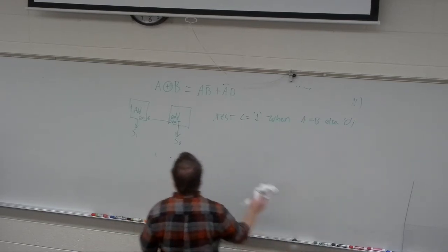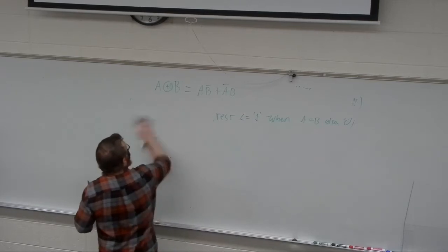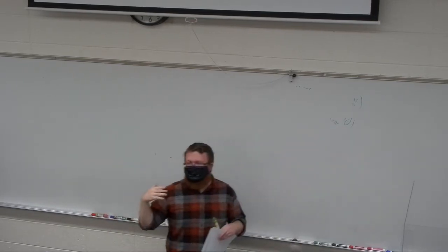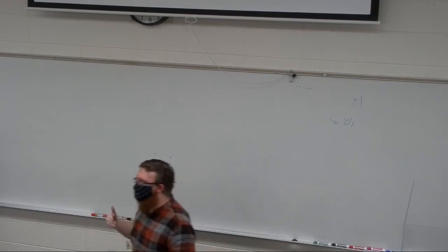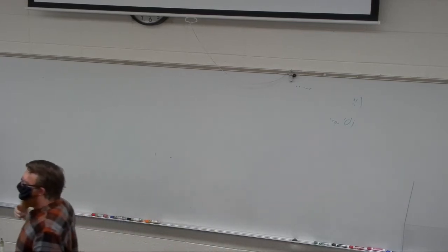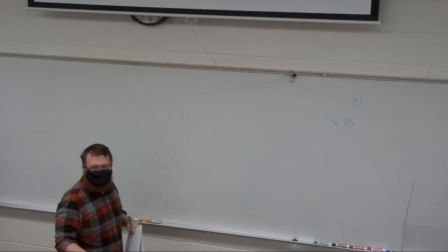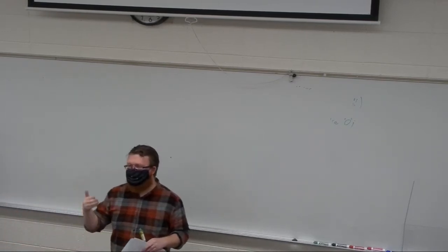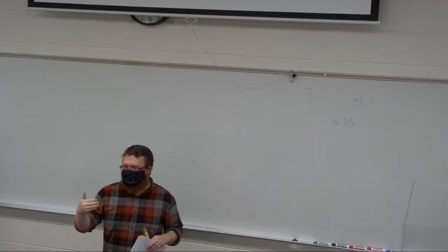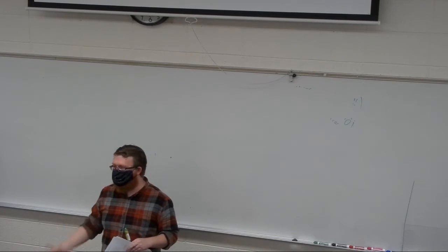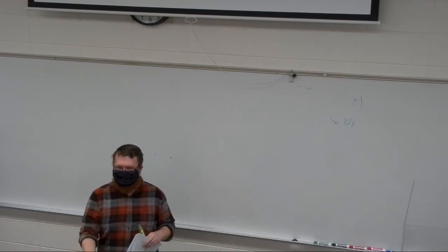And the general idea on a fast adder is simply that you can know ahead of time if you're going to create a carry, right? Simply by knowing A and B, essentially. And there's another idea of propagating a carry.